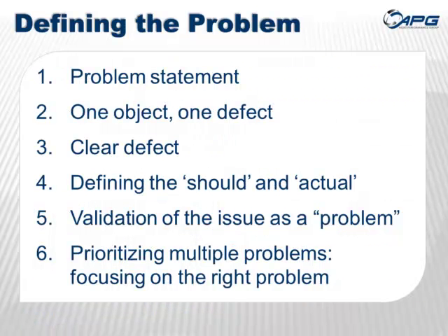All right, so let's talk about this first step, problem definition, for a minute. The first step we feel in a good, effective root cause failure analysis is to state the problem very clearly. At this paper mill where I went to conduct a root cause failure analysis, the presenting issue from the team was beater pit overflowing. As we talked about it at some length and clarified what the issue was, eventually we came down to a very different and, I think, far clearer statement of the problem, which was pump 2 fails to drain the pump well. Now, it took us almost an hour just to get to that point of clarifying what our problem statement was.